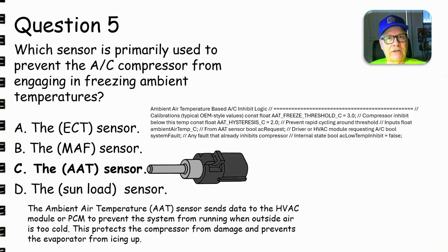Well, you get a potentiometer and hook up to this thing, have it running in the condition where the fan ought to come on, and even with the engine stone cold, you can use your potentiometer hooked between the signal return and the ECT signal, watching your scan tool, dial the temperature to the point where the fan ought to come on, see if the engine controller will turn it on. There's all kinds of things you can do. But this is the opposite end of that.